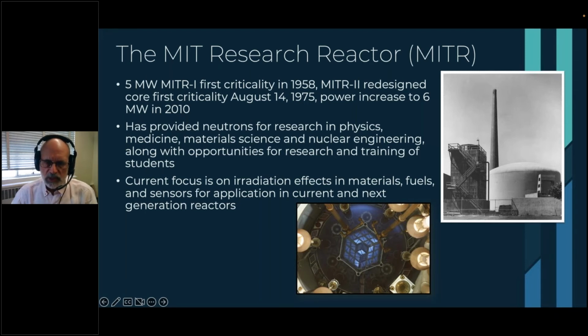We replaced the whole core and went from a heavy water cooled and moderated to a light water cooled and moderated, heavy water reflector design in the early 70s. And we followed that up with a power increase from 5 megawatts up to 6 megawatts in 2010.